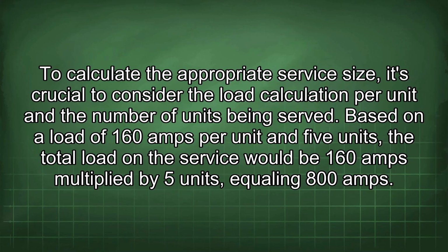To calculate the appropriate service size, it's crucial to consider the load calculation per unit and the number of units being served. Based on a load of 160 amps per unit and 5 units, the total load in the service would be 160 amps multiplied by 5 units, equaling 800 amps.